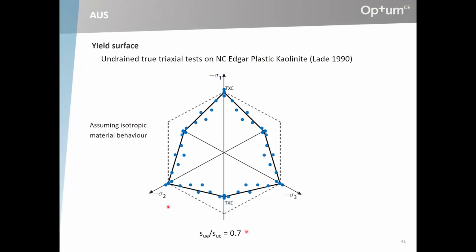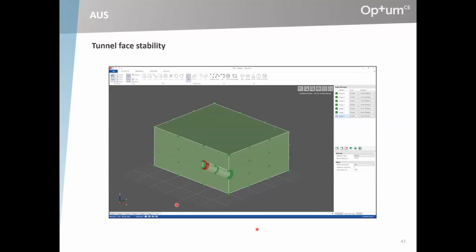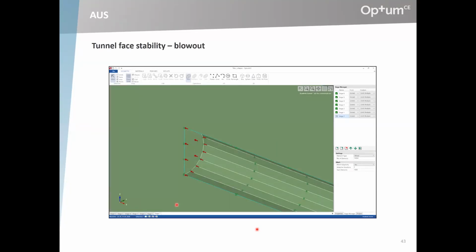So when we look at clay in 3D, we should make reference to at least two strengths, the extension and compression strengths. And the question is, what does it mean in terms of the strength and deformation characteristics of typical geotechnical problems? Well, I've looked a bit at the tunnel face stability problem recently. That problem involves tunneling with a pressurized tunnel head. You want to keep this tunnel face stable, and you can stabilize that by, for example, air pressure or some sort of pressure.